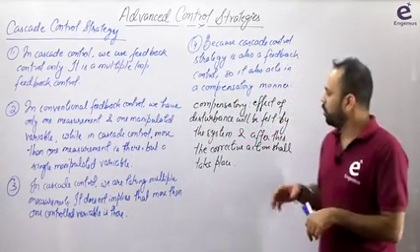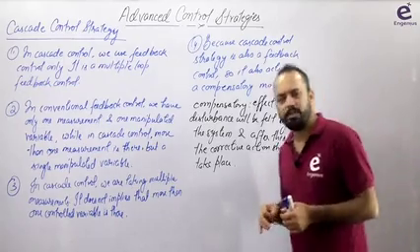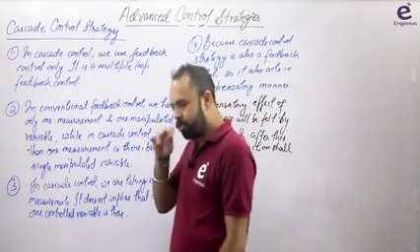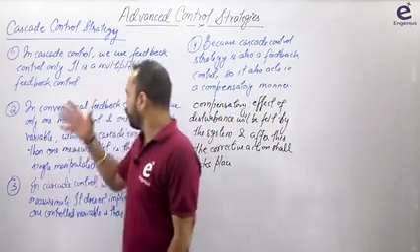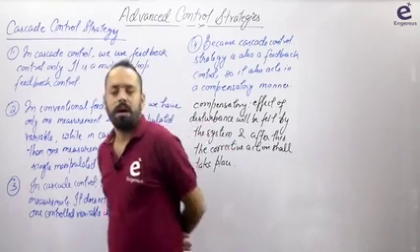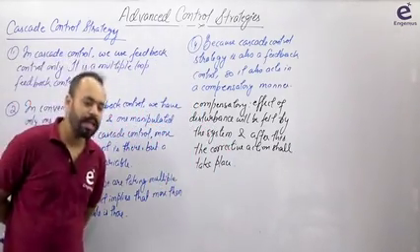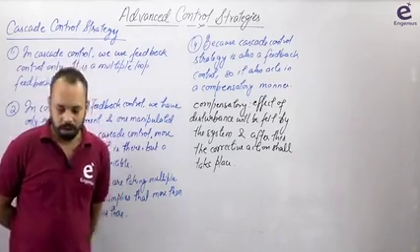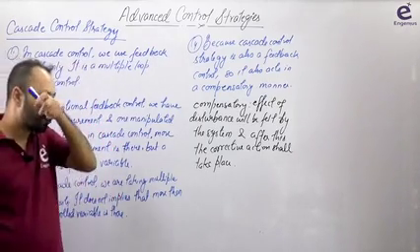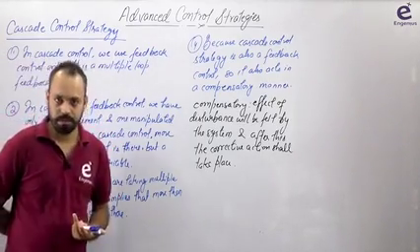So feedback control is a kind of compensatory control, and cascade is also a feedback control, right? So now the question, these are the characteristics. Now the question arises, sir, if cascade is also a feedback control, and there are a few differences as I discussed here, in which case is it good to use cascade, or what are the examples where we use cascades? So let me give you a few examples, and I'll show how cascading is used.